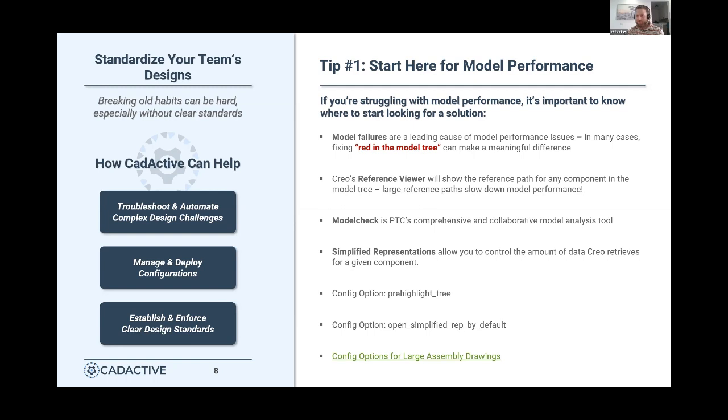Yeah, absolutely. So there's really three that I want to talk about right now. And the first of those is one that everybody should be familiar with. It's master rep. That's just by default, when you open a model in Creo, you're in master rep. What that basically means is that we're going to fully load everything that is in the model tree. So that's just a default rep, right?